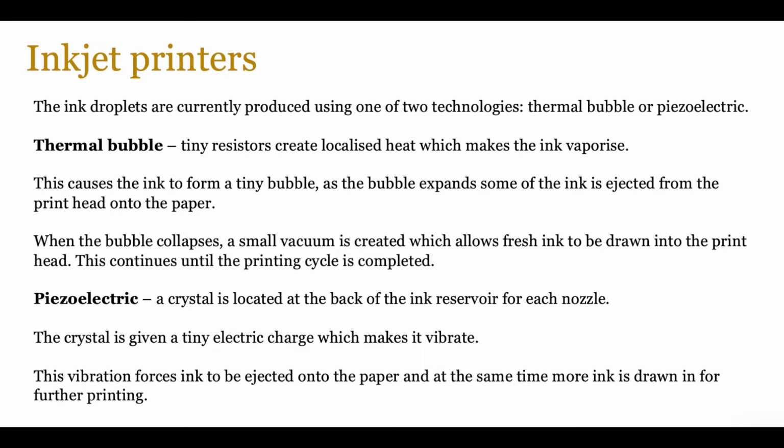The piezoelectric one uses a crystal which is located at the back of the ink reservoir for each nozzle, and the crystal is then given an electric charge which makes it vibrate, and the vibration forces the ink to be ejected onto the paper. When that happens, more ink is drawn in for further printing, and the process keeps on repeating. So they both use different types of technologies, but they have the same type of operation.